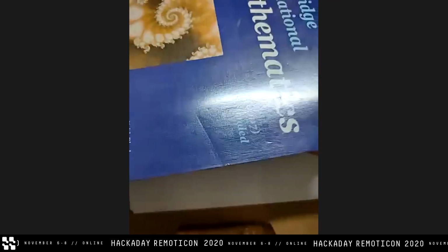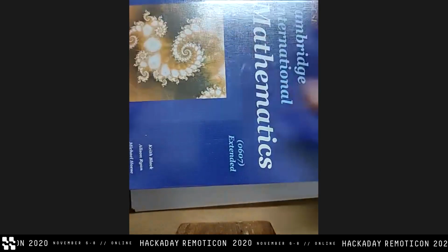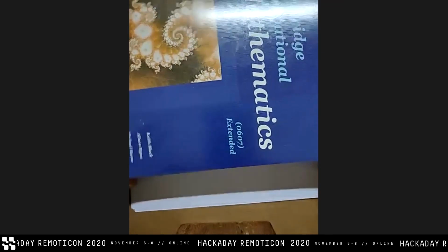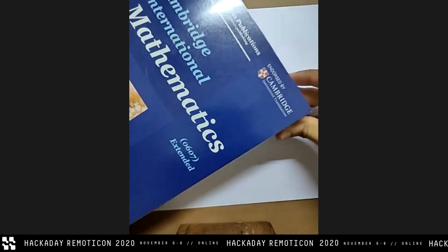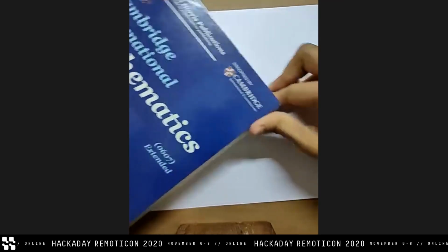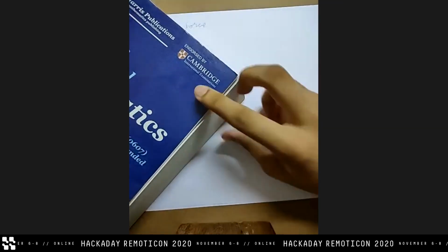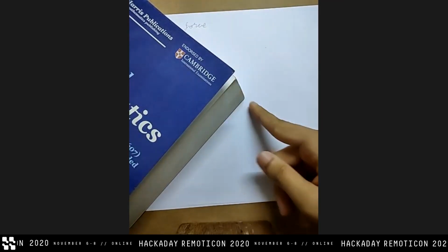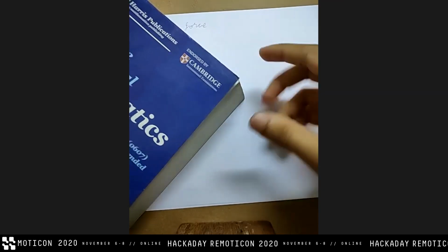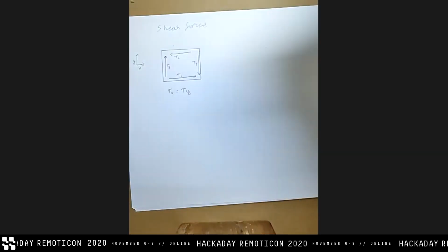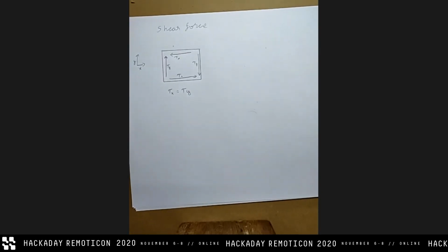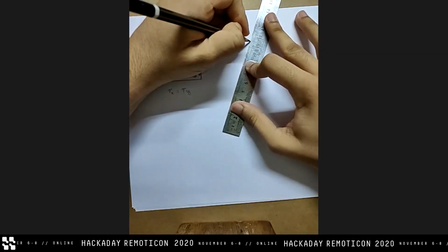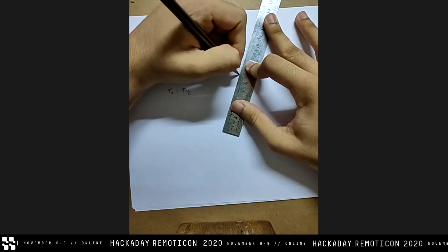But now let me see. If I try to shear it, so I'm pushing it along from the top only, you can see that the pages here slide over. It's not very visible, but you can see over here that these pages are sliding over. It's coming at some kind of angle. So now I can actually describe that. If I look at my deformed body, let's not make it on the same diagram. So this is my deformed body.